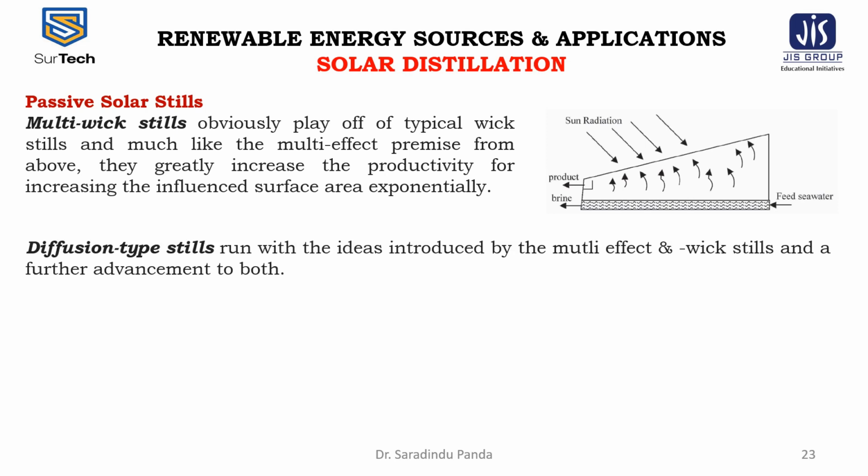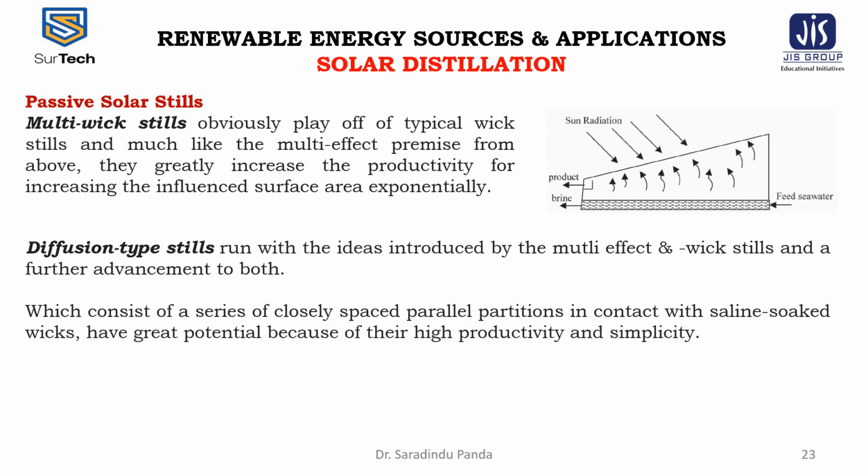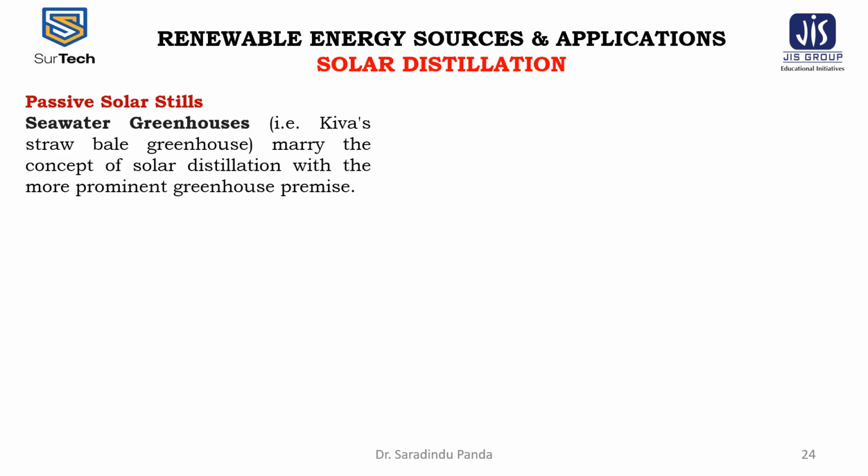The diffusion type of stills runs with the ideas introduced by the multi-effect and the wick stills, and as a further advancement to both, they consist of a series of closely spaced parallel partitions in contact with saline-soaked wicks, and have great potential because of their high productivity and density.